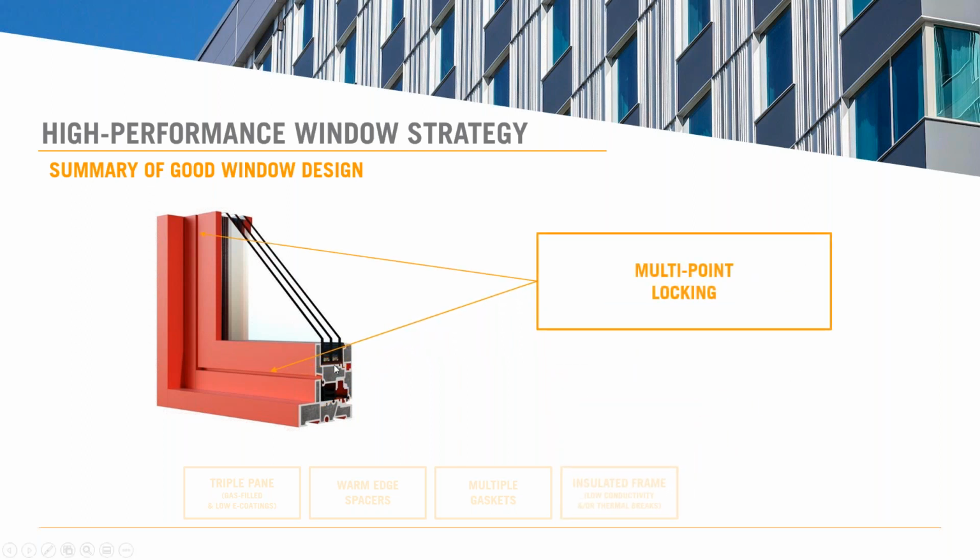To that last point as well, often weaker window materials such as PVC, in order to do larger windows, will have reinforcing in those cavities that can be steel or some other higher conductivity material. So it's just a consideration to take into mind when you're looking at your windows.